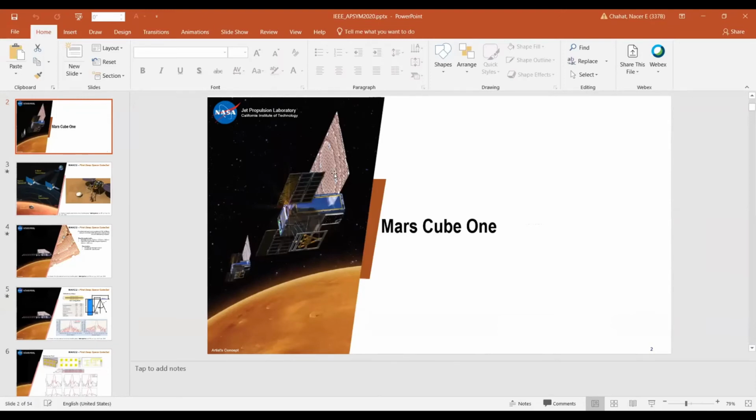Okay, I think, so just to be clear, a reflectarray is not a patch array. They do look like a patch array, but it's not. It's a resonant element where we change the size of them to change the phase across the surface of the reflector. So the reason why we have the reflector on each side, the same pattern, is from a thermal point of view. If you have a perfect symmetry on the reflector surface, you reduce the surface gradient across the surface. And so the surface will not bow as much. So that's the reason why it's very important to have something perfectly symmetrical.